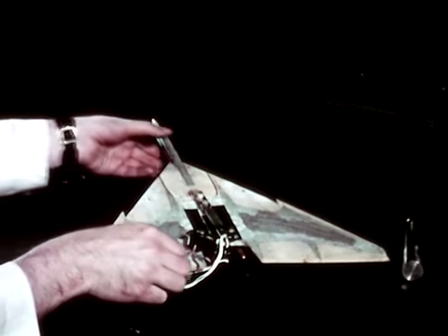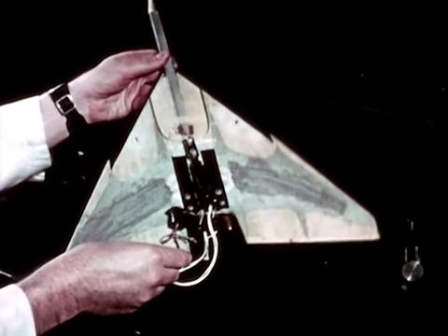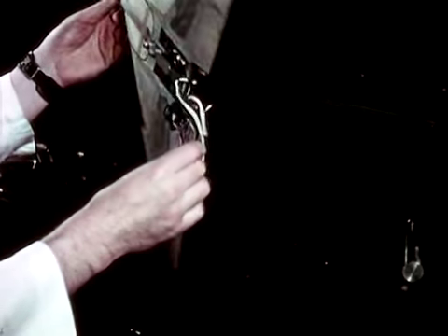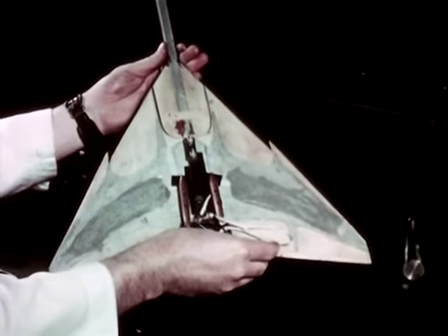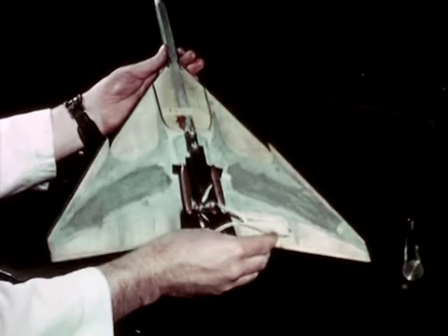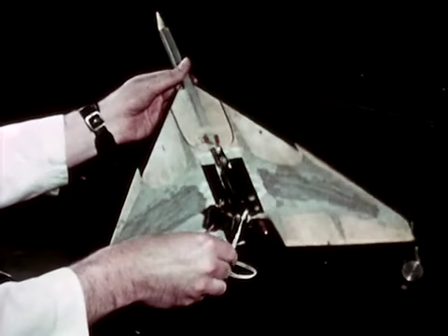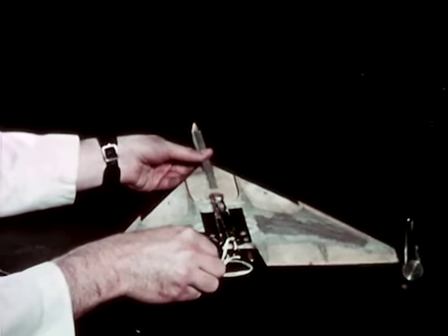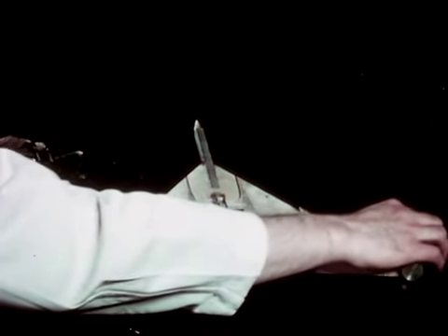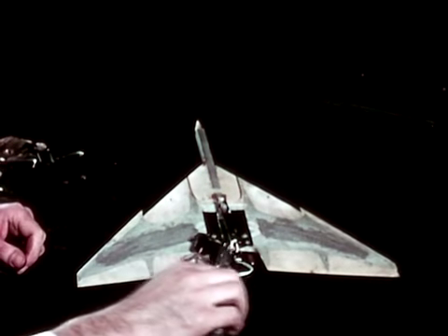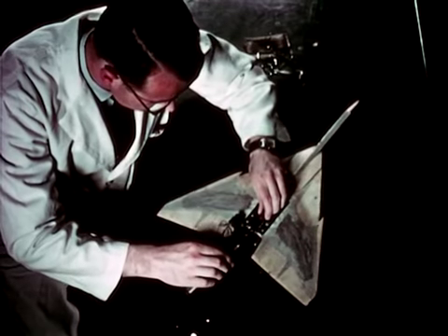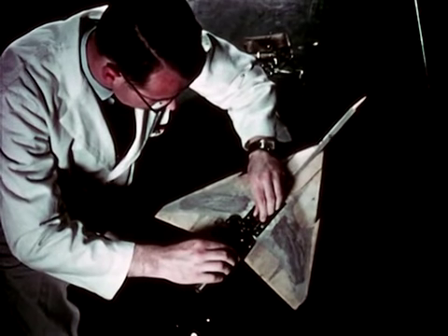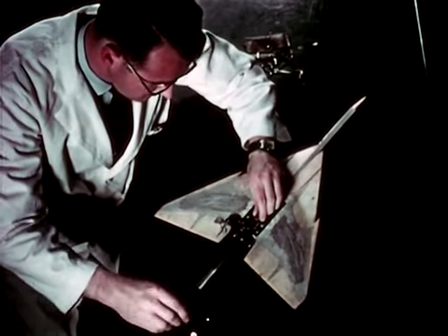On completion of the cantilever tests, full-span models were built. To avoid choking the tunnel, the fuselage area had to be reduced, requiring external concentrated masses to simulate the engines. The wing construction was identical to the cantilever type.